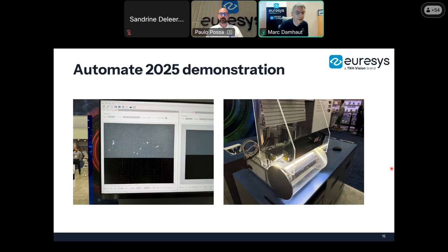And this is the result. You see the setup again on the image on the right, and then you see the images that are acquired on the left. During the acquisition, it is the job of the Coaxlink card to separate these lines coming from the camera and to store them into two separate images in host memory. So we end up on the top of the image here with the bright field illuminated image, and at the bottom of the window, the dark field illuminated image.